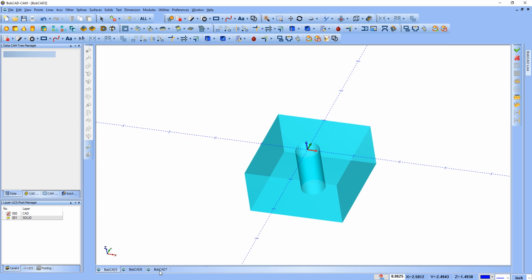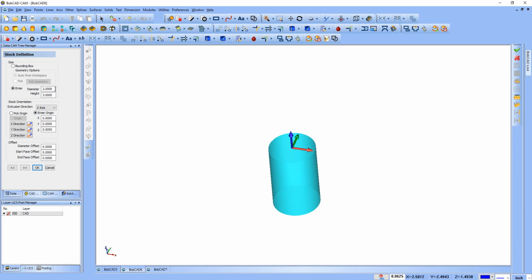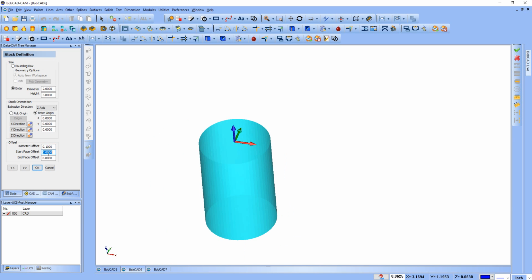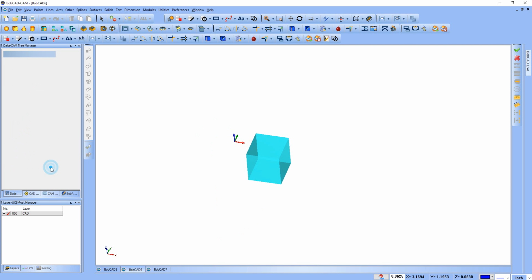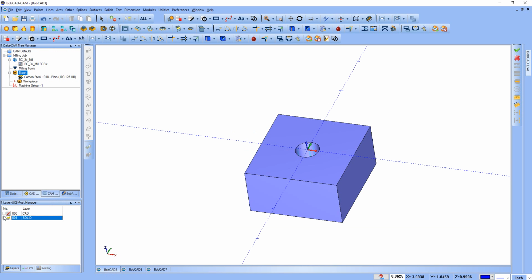So say, bounce back over to this page. Stock wizard. If you want to do a cylinder, again same thing, diameter 2 inches, 3 inches in height. You want it on zeros for X, Y, and Z. Say if you want to do a 0.100 diameter offset, you can see it gets bigger. Base offset. You have your different options. So it's pretty easy to set that up. It's just if you don't have anything set up, then it's going to make you set it up. That's really the only real restriction to being able to run the toolpath. You had to set that first.